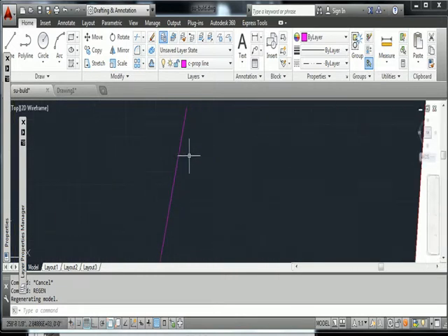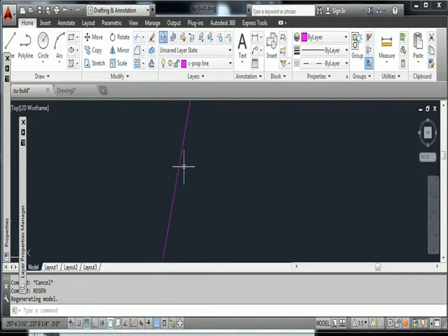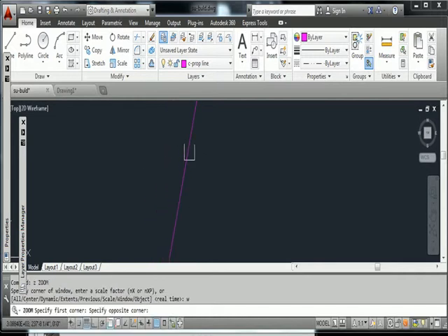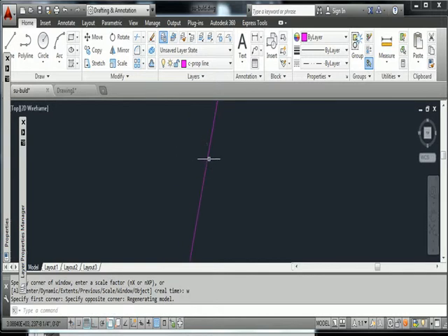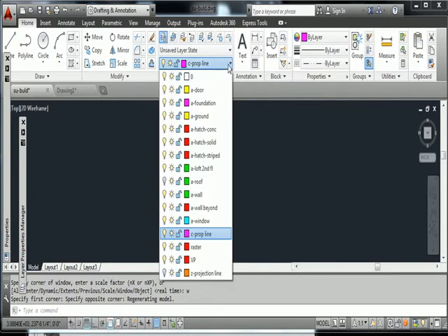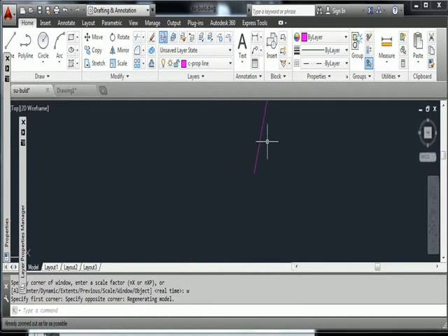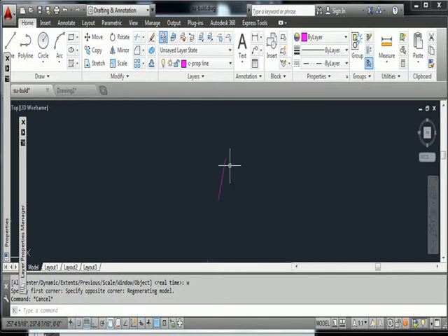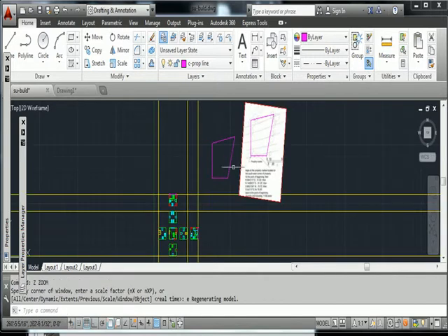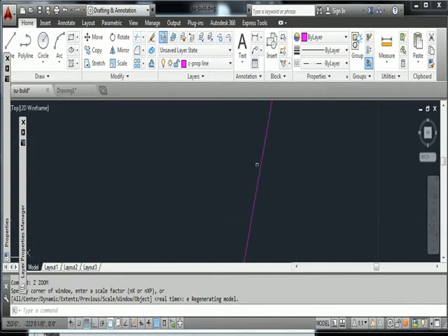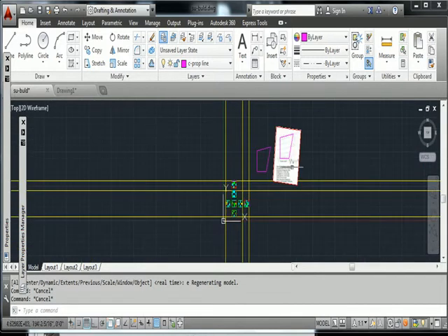If you zoom way in there, it is zoom window. Wait a minute, this is... I feel like yours actually did. Oh, I know what's wrong. There it is. I have zoomed in too far. You're in too far. Zoom extents. Okay, so when you zoom in, you should be able to see that. However, don't worry about how it appears in model space. It's what appears in paper space that's going to be the key to that.